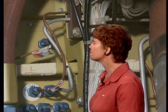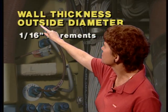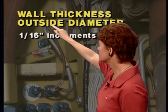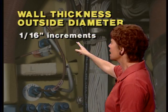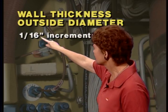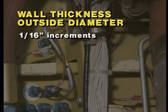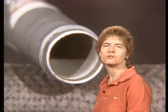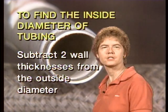Now, when you're working with metal tubing fluid lines, how are they sized? Well, they're sized by wall thickness and also by outside diameter, not inside diameter, but outside diameter. And the size increments that are used are increments of 1/16 of an inch. Now, with tubing, to find the inside diameter of tubing, what you need to do is to subtract 2 wall thicknesses from the outside diameter.